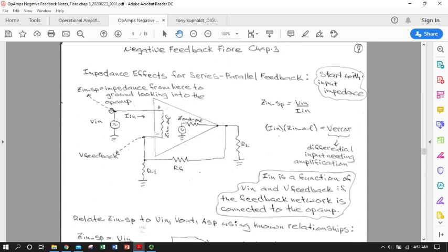But regardless, I can always define the potential and the resistance or impedance of this point with Ohm's law, because from the standpoint of this point, I've got a certain amount of current flowing. How much? Don't know, but there's some current flowing, just a little bit. So I can define my input voltage, which I have a source that just gave it to me, as whatever this input impedance is times whatever current is flowing. So Zn closed loop is equal to Vn over In.